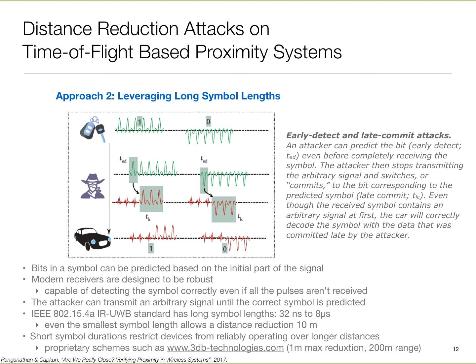Those of you who may have done a communication course may have heard of this term called Eb over N naught, which is essentially energy in a bit or symbol relative to noise, and the higher the Eb over N naught, the more reliably you can decode the signal, okay? It goes back to Shannon's communication theory. So one of the ways we make this energy in the symbol larger is to stretch it out, slow signaling over a long time. Or in more sophisticated methods, instead of sending a single symbol when I'm sending a bit, I send a train of symbols, okay?